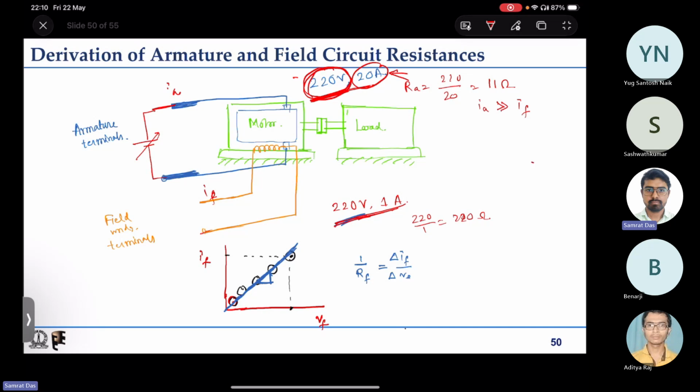Suppose you have a motor that has some back EMF of 200 volt, and you have some winding through which you want to pass 20 ampere, and say it has a resistance of 1 ohm. Now how much voltage will be required? The voltage VA has to be higher than 200 volt so that the current goes in this direction, and it has to oppose the resistive drop across the armature winding also.